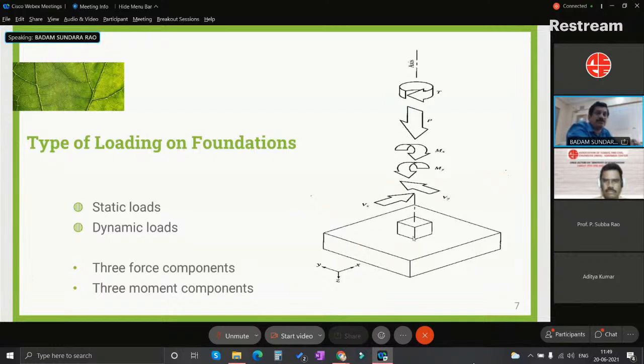One more factor to be considered in the design of any foundation system is that generally we design for the axial loads, ignoring the moment effect and the shear force effects. That is not a practical case. For an accurate design of any foundation, we have to consider all 6 degrees of freedom in an equivalent system, such that it is a combination of the vertical load and the moment acting on it. Especially, this is very important while designing a biaxially loaded footing, which comes across during the design of any bridge foundation or during earthquake loading.